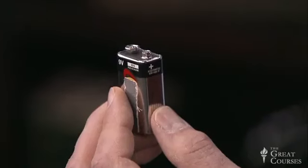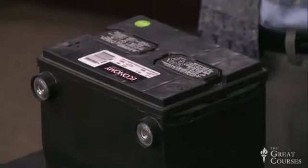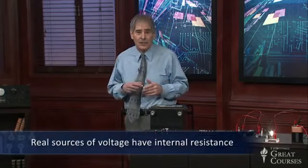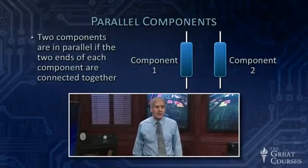Here I've got a little tiny 9-volt battery. It has a rather high internal resistance. And here's a car battery, 12 volts, not much different from 9. What's different is it has a vastly lower internal resistance. So real batteries, or any real sources of voltage, have internal resistance, and you have to take that into account if you're going to use them correctly. And you have to put loads across them that aren't too low so you don't drop a voltage across that internal resistance.